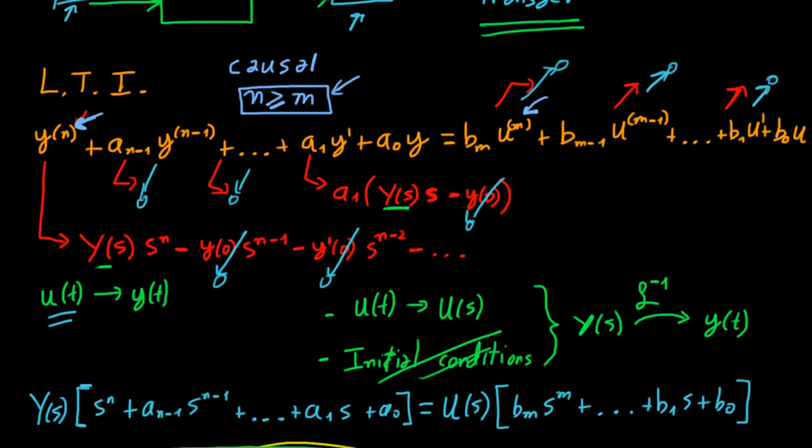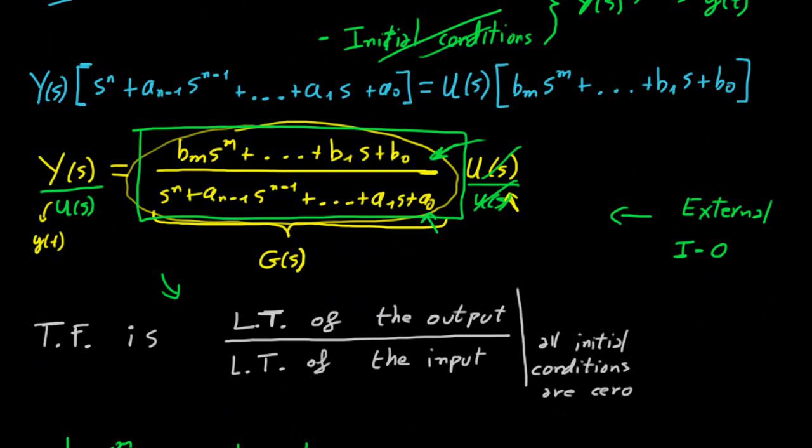So you can see that also in the transfer function. This exponent here must be greater than or equal to this. And if you come across a transfer function in which m is greater than n, you have to realize that there's some problem, that the transfer function is not describing a physical system, because it is not respecting the cause-effect relationships.